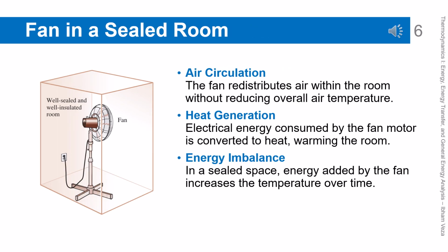Fan in a sealed room. A fan only circulates air without removing thermal energy from the room. The electrical energy supplied to the fan motor is eventually converted into heat. In a closed system, this added energy increases the room temperature. There is no mechanism to reject energy outside the system. This example shows that not all electrical devices can provide a cooling effect.